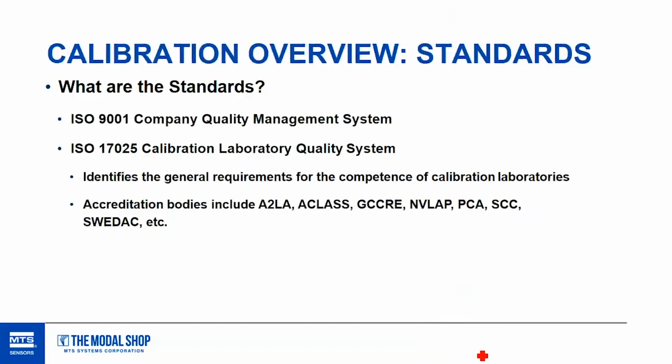Kind of cool. So, kind of wrapping up here, some of the standards that you have, obviously ISO 9001, if you want to look up some of the stuff, this is of course the obvious one. It's a company-wide quality management system. If you want to get specific, if you want to get accredited for these types of calibrations, or if you want to look to see that the calibration lab that you're getting your assets calibrated in is competent in calibration, the relevant standard there, of course, is ISO 17025.